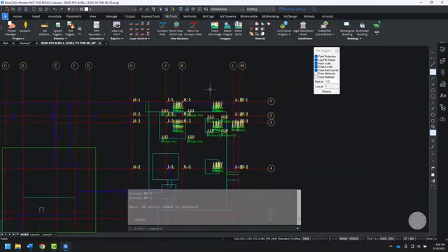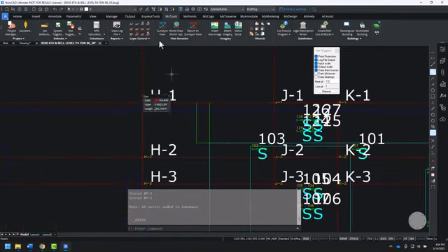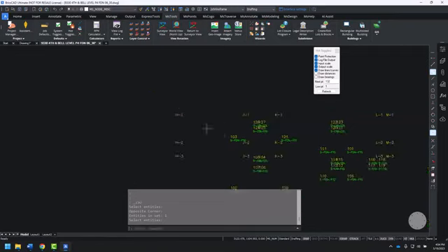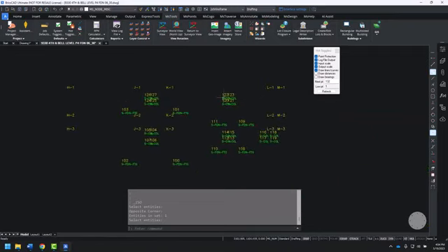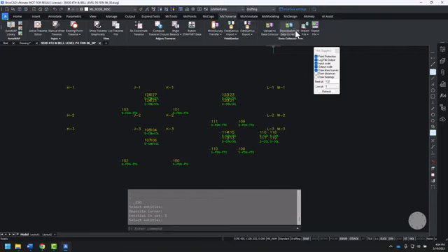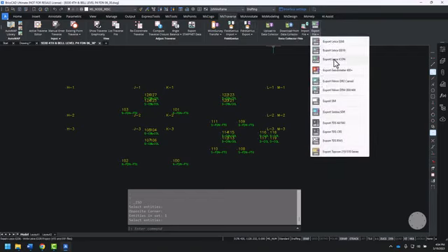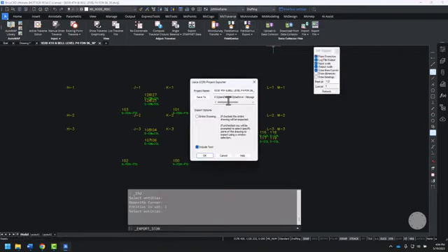We can see all of our points. And what I'd like to do is isolate just the point layer. Now that we have our points ready to go for stakeout in the field, MS Traverse, Export File, Export Leica icon, I can choose where I'd like to put it, in my Documents Exports folder, not the entire drawing.